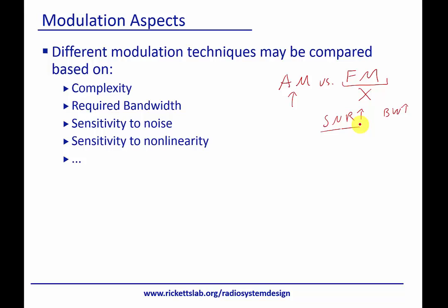So here's a great example where we would decide to do frequency modulation instead of amplitude modulation because it'll allow us to use a wider bandwidth, and as we'll learn later, that actually translates into a better signal-to-noise ratio. And that's why your FM radio sounds better, is because it can use a wider bandwidth than AM, and because of that it can get better sound quality.